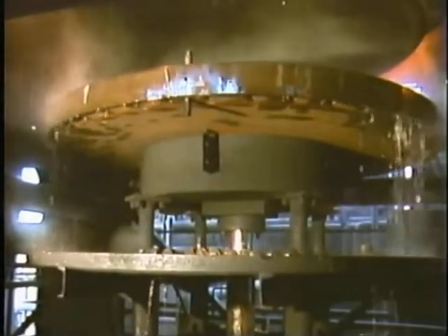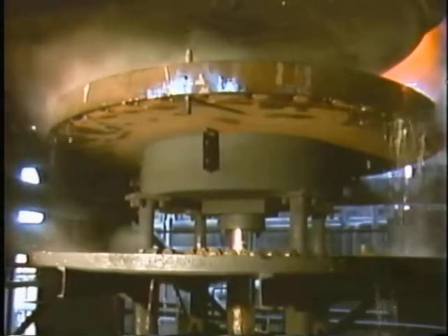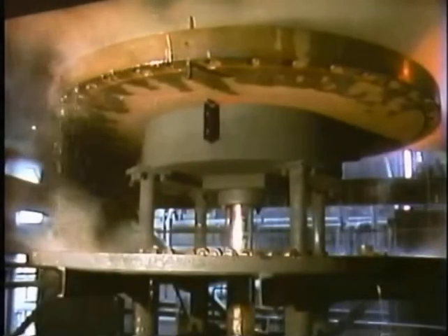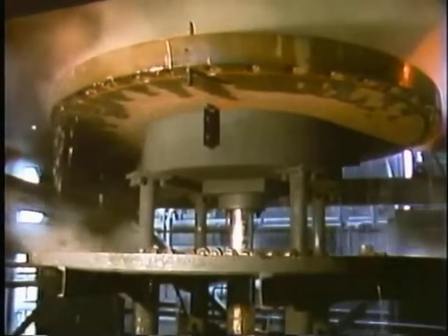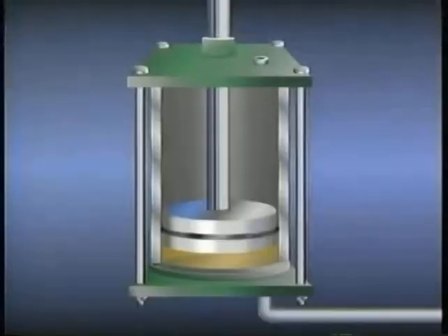In this actuator, fluid flow acts on only one side of the piston to raise and support a heavy load. When the fluid is allowed to flow back out of the actuator, the weight of the load supplies enough pressure to return the piston. Let's take a look at this illustration to get a better view of how this kind of single-acting actuator works. The main parts of this actuator include a cylinder, a fluid port, a vent, a piston ring, and a piston rod.